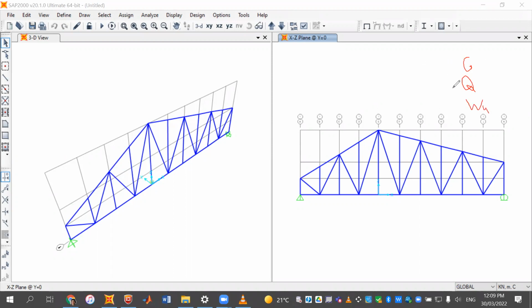And without any multipliers. So you have only G, only Q, and only wind load. So we are going to use those numbers here and apply them separately. We are not going to add them together because it is what the software will do when it combines the actions. So don't worry about them and apply them as separate loads.